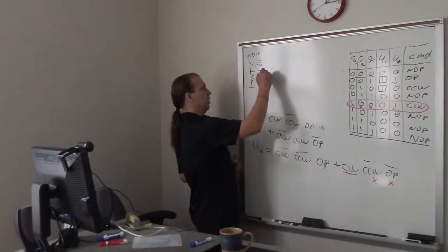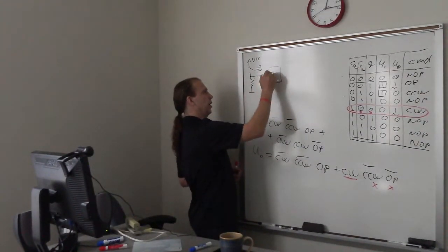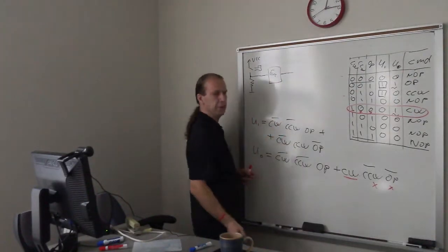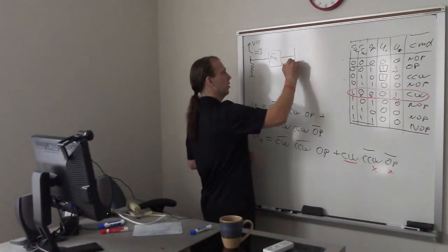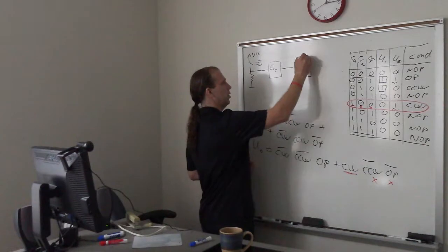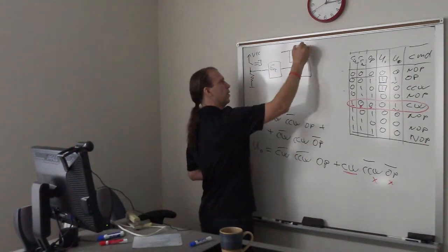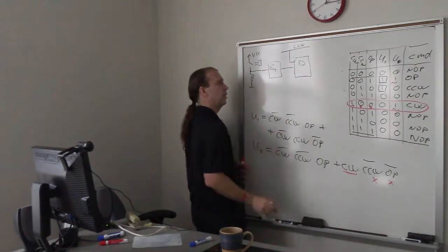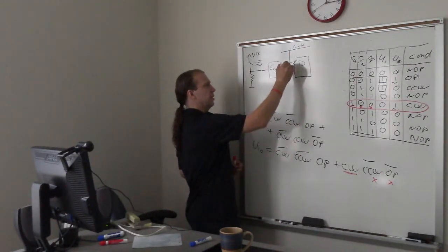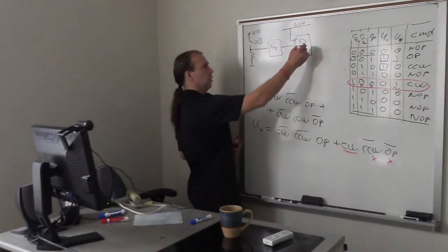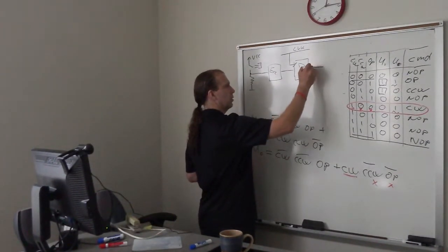So eventually it goes through the encoder, and then it comes to the input of a trigger. We want to use D triggers, which are going to be fed with a clock signal. And just a couple of moments ago I showed you the way a D trigger works. So this is the output.